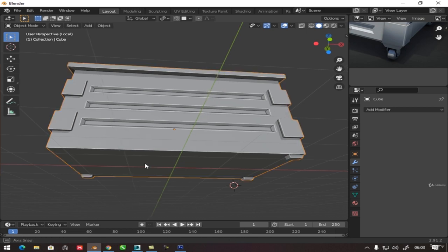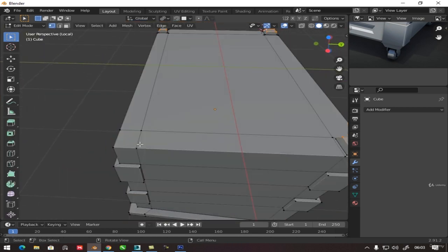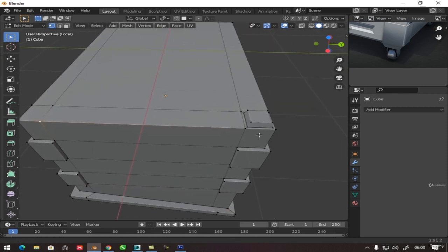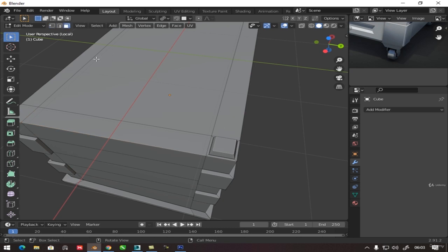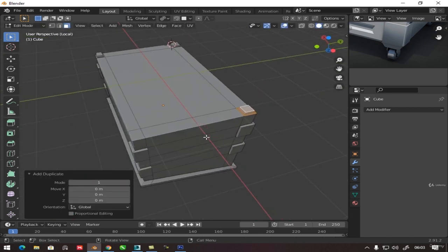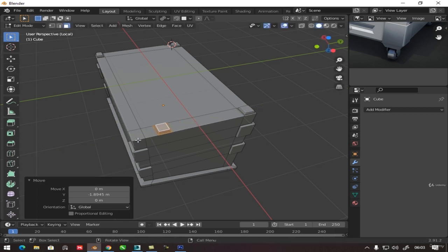And here it doesn't have the foot, I don't know why, so let me isolate it. It's missing one foot there. So, you know what I will do? I will get this face, Ctrl plus to grow the selection, and I will Shift D, right button, leave it in place, and bring G, Y, more or less to here, and delete this face.